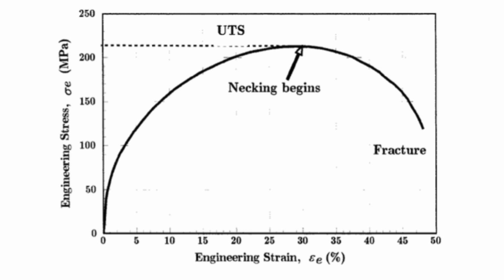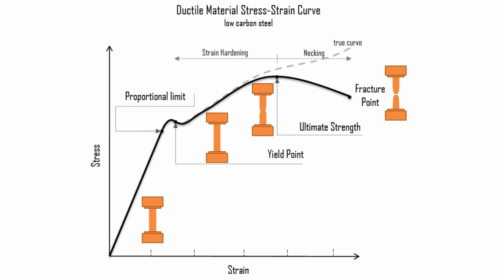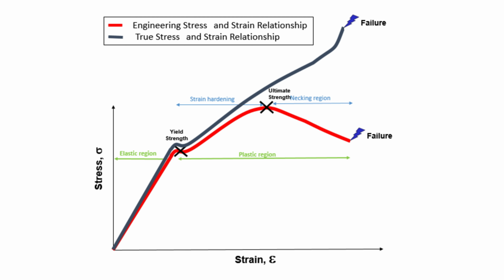Beyond the yield point, molecular flow causes a substantial reduction in the specimen cross-sectional area, so the true stress actually borne by the material is larger than the engineering stress computed from the original cross-sectional area. The true stress is not quite uniform throughout the specimen, and there will always be some location, perhaps a nick or some other defect at the surface, where the local stress is maximum.